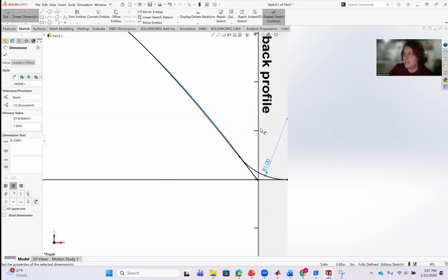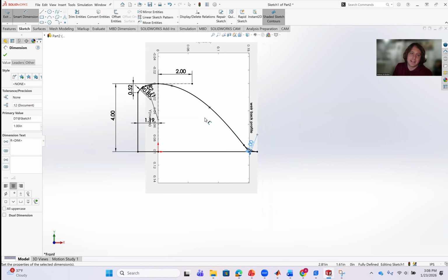You might see that in the publication it asks for a 30-degree arc, or sorry, 60-degree arc. At weirs of this scale, I found that it gets a little bit weird when you have that 60-degree angle. But the most important part from that geometry, in my opinion, is that they are tangent and the arc is smooth enough for the height.